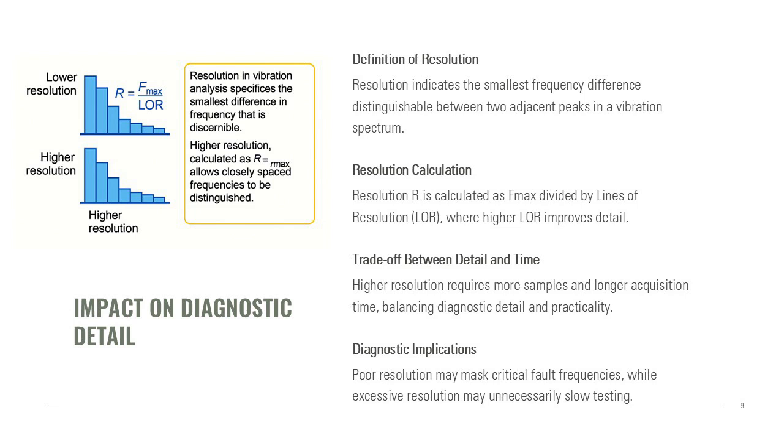However, higher resolution requires more samples and longer acquisition times, creating a trade-off between detail and practicality. Analysts must balance the need for fine resolution against the time available for data collection. Poor resolution can mask critical fault frequencies, while excessive resolution may slow down testing unnecessarily.